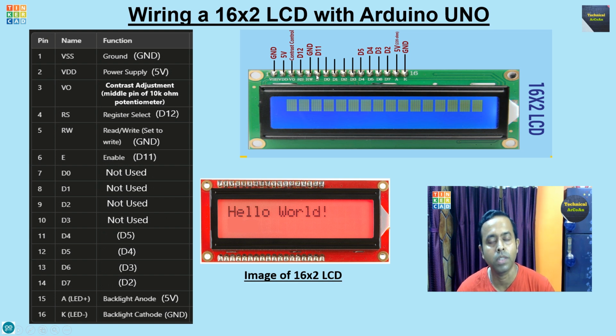Next one enable, connect with digital pin 11 in my sketch. And next 4 pins D0, D1, D2, D3 are not connected. We just leave these pins. And after that, from D4 to D7 respectively, that is D4, D5, D6, D7 connect to digital pins 5, 4, 3, 2 respectively, right? And next the anode directly connects with 5 volt with a 220 ohm resistance, right? And the last pin, which is pin 16, the cathode, connects with the ground, right? So in that way the LCD should display like that. Here we print hello world.